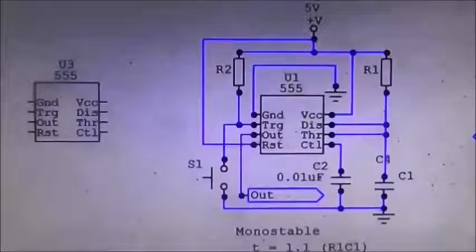And so before us we see the pin out of the chip and set up as a monostable. And if we consider the insides of here, I'm going through the pins, we have the VCC, which is positive supply, and ground, which of course goes to the negative rail. And between those we have a series of resistors. There are three linked together, and they are each 5 kilo ohm, which gives the timer its name, the 555.